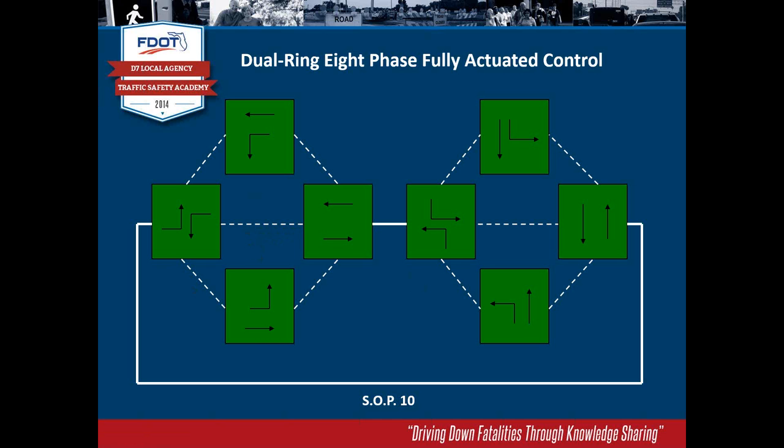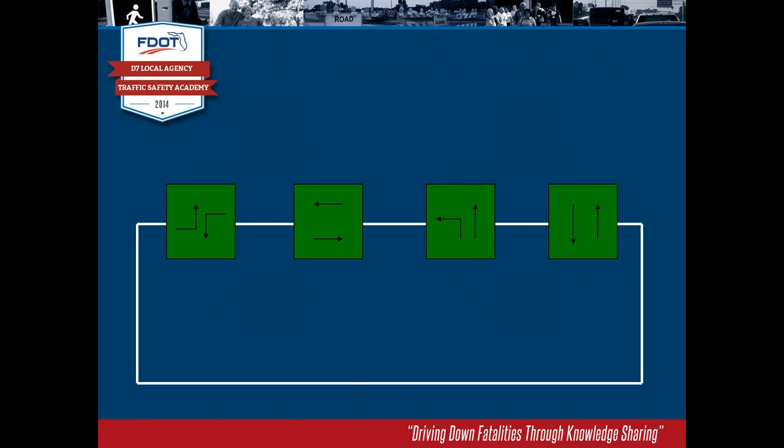All right, so in the example we just gave, let's look at what would happen here. We had eastbound and westbound lefts very heavy, eastbound through heavy also, no southbound left demand, but we have northbound lefts, and northbound and southbound throughs do have demand. And so what we end up with is this sequence of phases out there on the street, if you will, where we had, again, eastbound lefts max out. We said they're heavy. And so then we go to the throughs. Then we had northbound left and throughs.